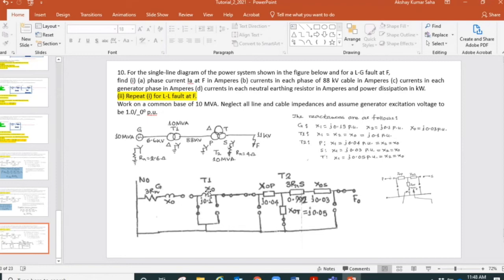And then I come to the transformer. This is the transformer winding and it's delta, so this star connection side cannot be connected or closed, it's left open, this is delta connected, so the shunt is closed. We come to this 88 kV side, we see that it's star grounded, so that is closed, and the shunt cannot be closed because it's star connected, it's not delta connected. So we're done with transformer 1. Is that clear? Up to transformer 1, if it is clear, let me know. Is it clear, or do I need to explain it a little more?